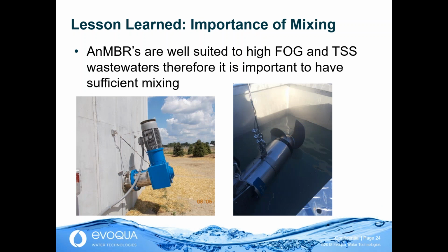Kind of in concert with the screening is the importance of mixing, because mixing is what provides the contact between the substrate and the biomass. So we need to make sure that the CSTR is completely mixed so we get that good contact, so that we get those good removals that we were talking about.